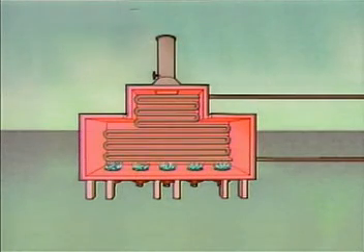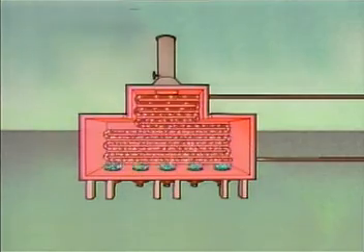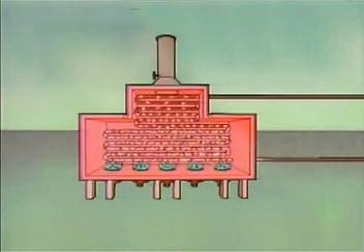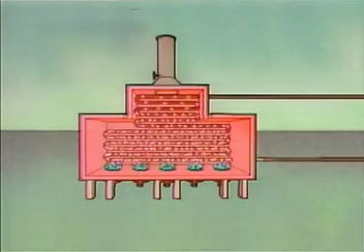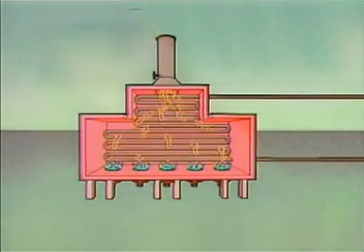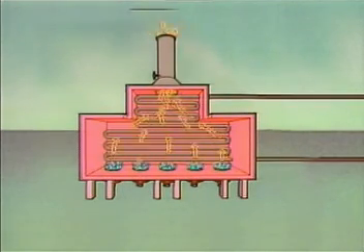In the second action, heat released by the chemical reaction created by burning fuel is transferred to the process fluid. The fluid flows through the tubes inside the furnace and receives heat by conduction, convection, and radiation heat transfer. In the third action, the combustion gases that are produced by burning fuel rise through the stack and are exhausted to the atmosphere.